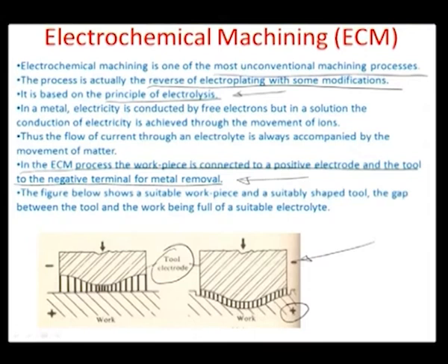And one good point that I would like to mention here is that it's a die sinking process, meaning thereby that whatever is the profile of the tool, however complicated the profile of the tool may be, is eventually impressed into the workpiece surface, because of the non-uniform distribution of the electric field to begin with.